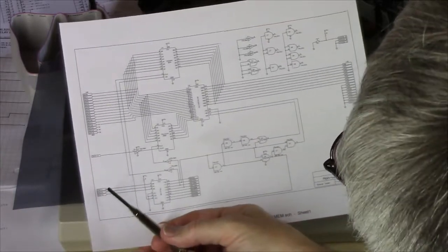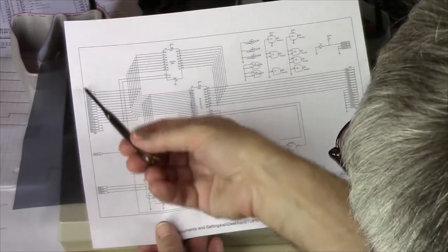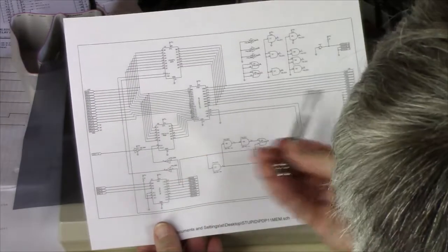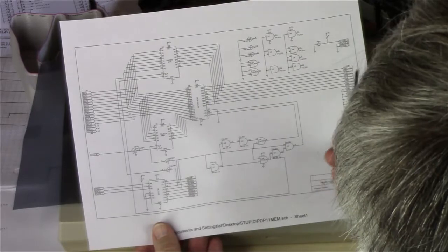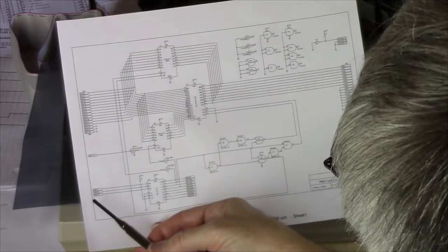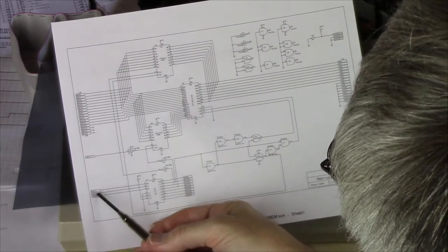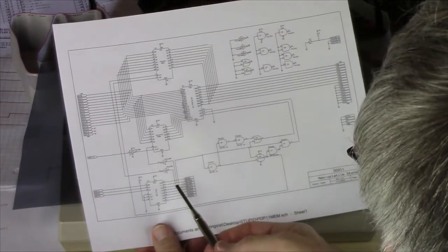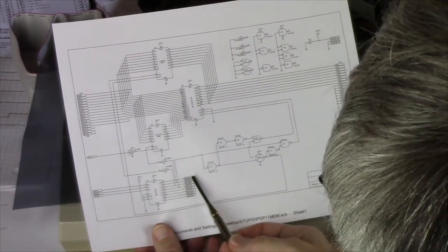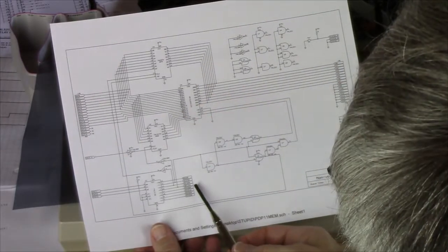And then there's a control and status register. So there's one register on that card that holds the output data and input data. When we're reading, we come here, and that'll show up in that data buffer. And then there's a control and status register, which has these function bits. There are 3 function bits. So I'm actually only doing 4 operations right now. We can read, we can set the page register, we can set the data register, or we can do a write.